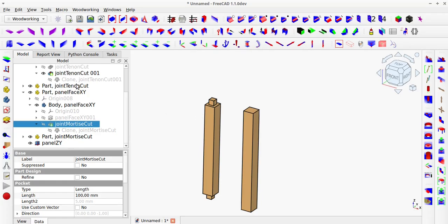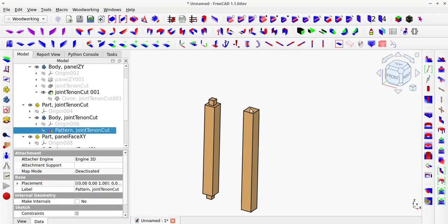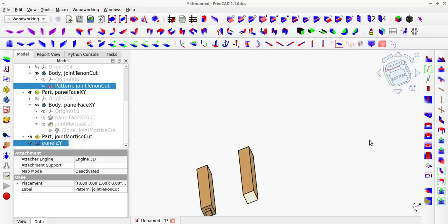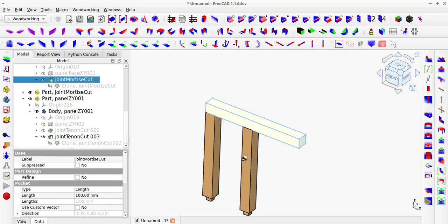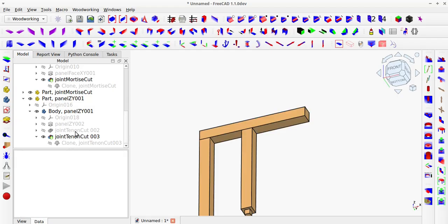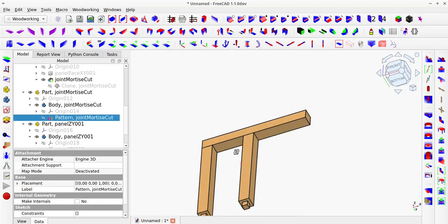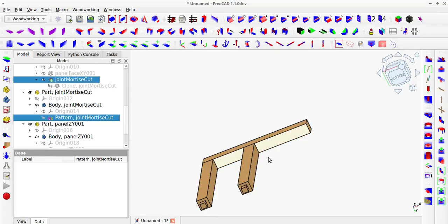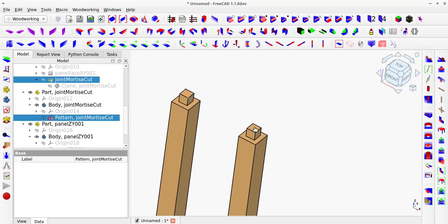In this case, however, the directory structure is much simpler and allows for the construction of much more complex models. In this case, you can also continue adding new mortises to an existing sketch. Simply select the sketch with the current mortise pattern to cut, then the face to cut, hide the object, and then all the tenon faces. This is quite complicated, but after a few attempts it goes very quickly.